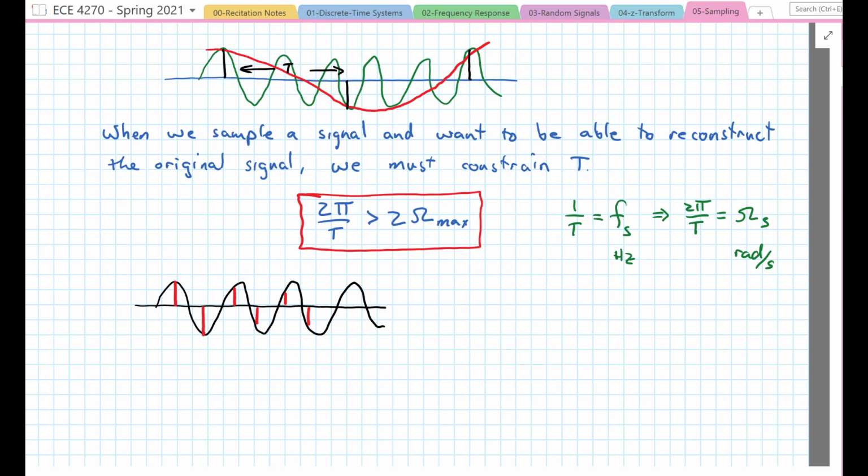Note, if on the other hand we had exactly 2 samples per period, we might run into a problem. Just to illustrate this problem, here is a set of samples that are 2 samples per period. In green there, and those ones would obviously not be useful in recreating the original signal because it would all be zeros. So we have to have greater than twice the highest frequency needs to be our sample frequency.